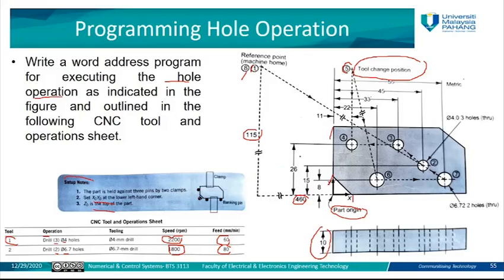The most important thing is that you need to define the coordinates and the place for each drill. You need to select your correct workpiece dimensions. You need to select your correct tool with the correct diameter, and you need to specify your parameters, like speed and feed rate and so on.